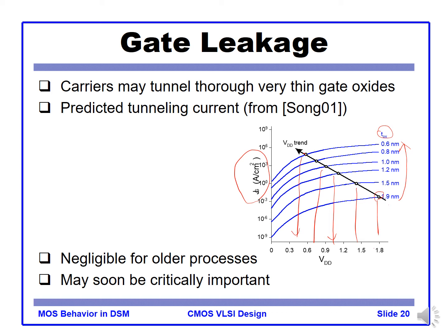especially for mobile applications like a cell phone. You want to have your cell phone running longer. So the gate leakage was negligible for older processes, but we will see some critical point where the gate leakage is large. But currently the biggest leakage is the subthreshold leakage current or off current, like between drain and source. There's always non-zero leakage current there.